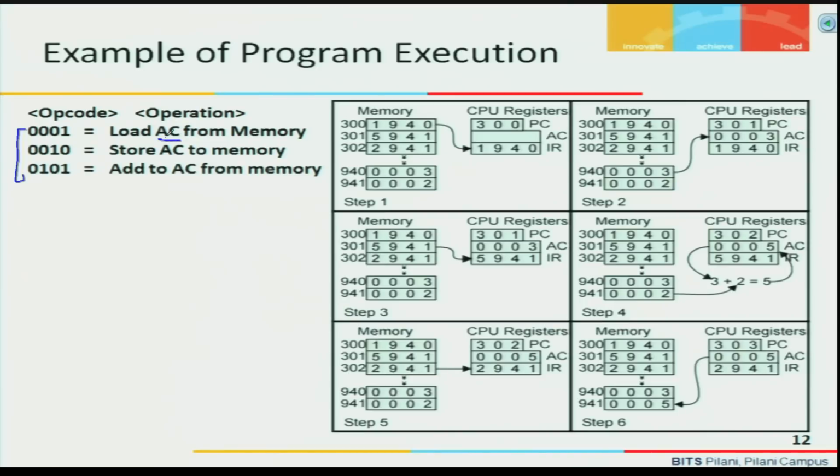AC is the accumulator register, it's one specific or special purpose register called the accumulator. If you are using the load instruction, you say load AC, meaning the data from the memory location specified in the load instruction is loaded, and where the data will be put, say simply if you will say load A.